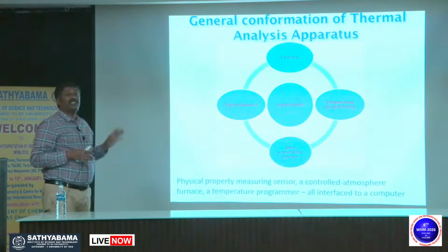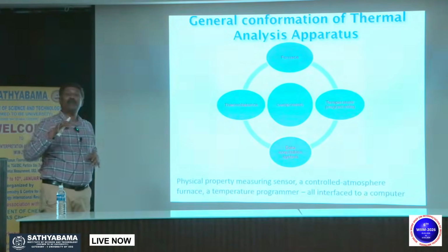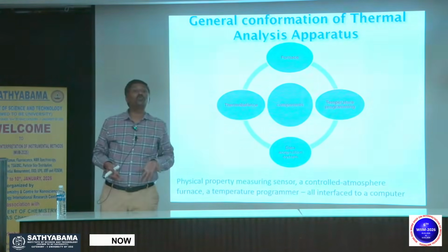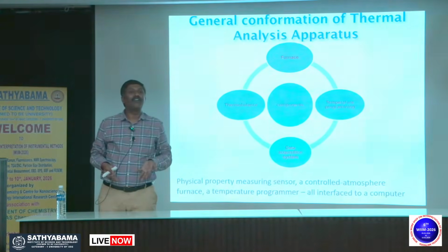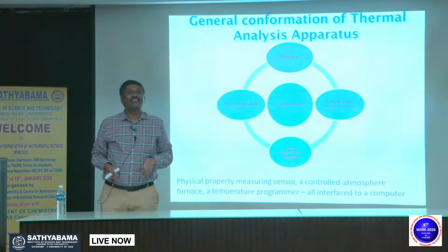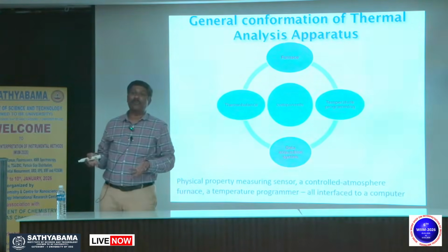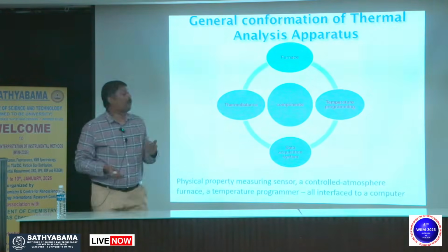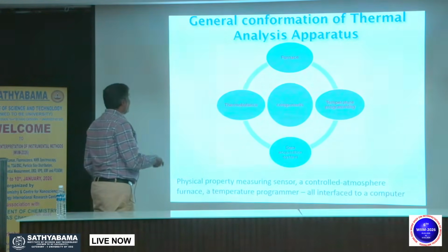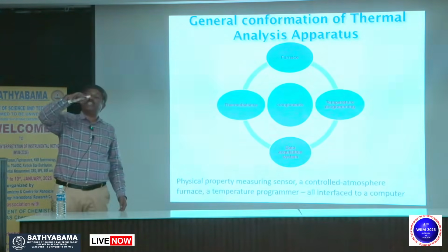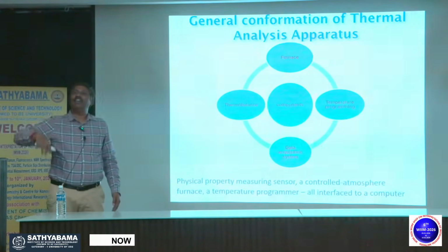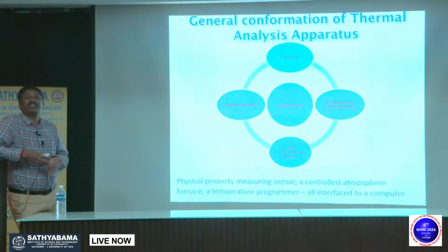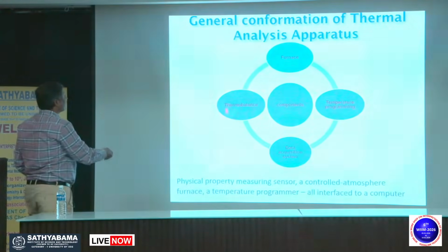So, a furnace where you have a sample chamber and heating facility, and programming. How much you are heating, you should know, isn't it? At what rate you are heating, you should know. So programming. At that higher temperature, it should be able to perform either heat change or mass change. So there should be a thermal balance.